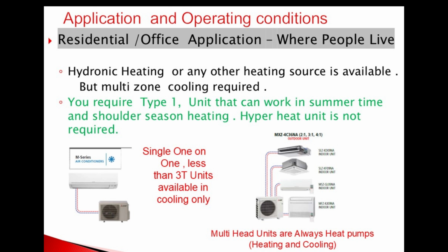If your cooling capacity requirement is under 3 tons, you can opt for a cooling-only unit. However, for multi-zone systems or capacities above 3 tons, you'll need a heat pump. Keep in mind, though, that heat pump heating is best suited for shoulder seasons like fall and spring.